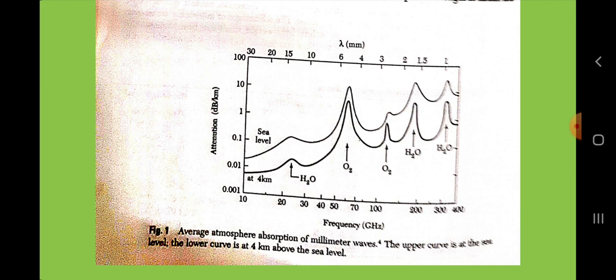The distributed effects must be taken into account at microwave frequencies because at these frequencies the wavelength approximates the physical size of the components. At microwave frequencies, a thin film resistor, for example, looks like a complex RLC network with distributed L and C values and for different R values. These distributed components have immense significance at microwave frequencies, even though they can be ignored at lower frequencies.